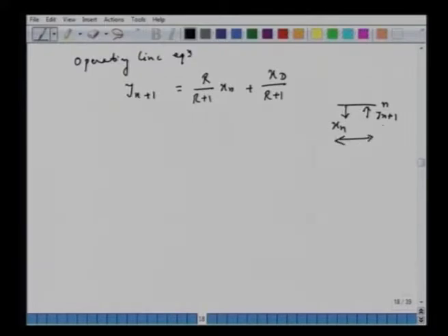It connects y_{n+1} and x_n by this equation, which was obtained, if you recall, by taking this envelope region 1 around this condenser and the nth plate to write this material balance. So we know the reflux ratio now, R equals L0 by D. 1.3 is given to us, that reflux is 1.3 moles per mole of feed sent as condensate, over D, which we have calculated as 0.3, to make it 4.34.